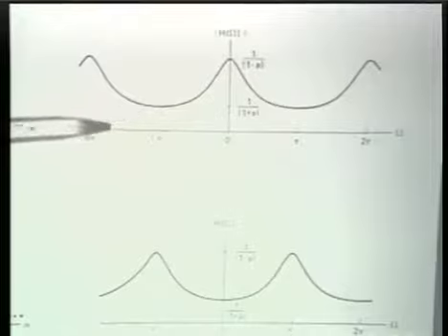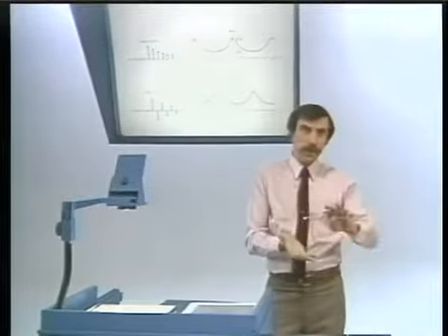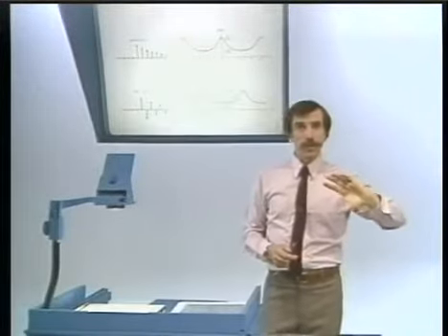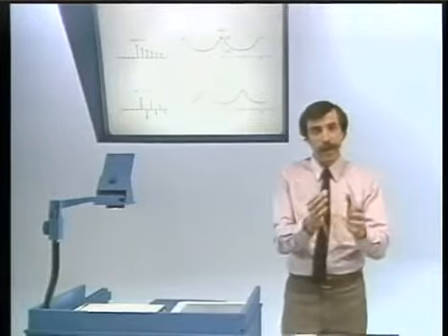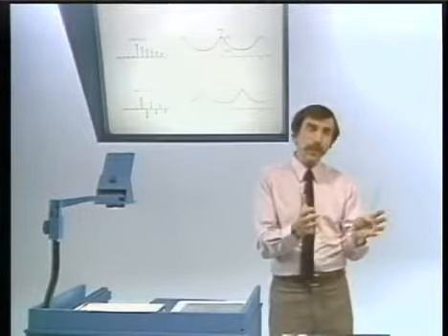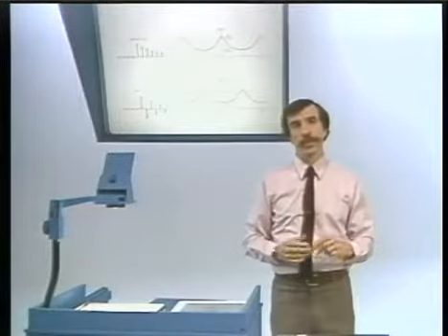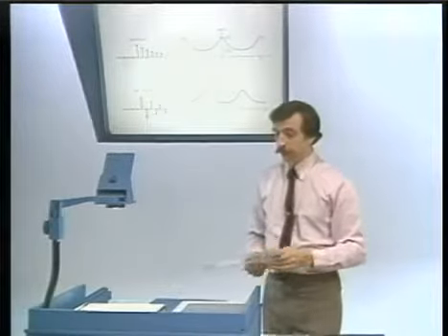So it says, in fact, that if we think of a positive and a negative, that is algebraically similar to multiplying the impulse response by minus 1 to the n. And in the frequency domain, the effect of that essentially is shifting the spectrum by pi. And we can interpret that in the context of the modulation property.